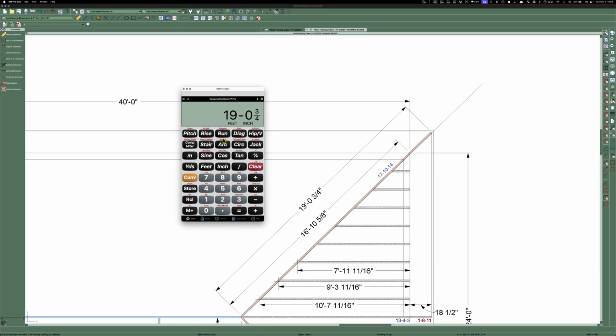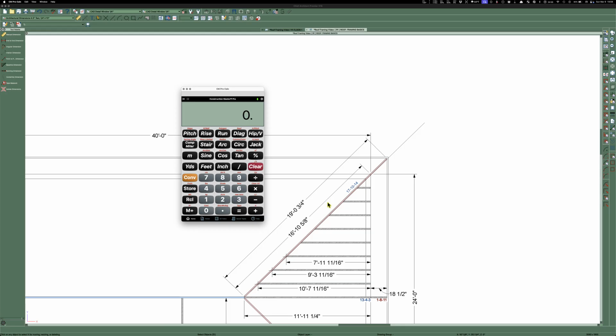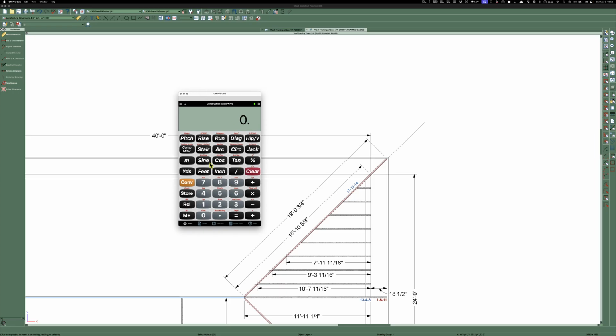I wonder if it'll let me do this. Yeah, hold on. Because really, people will say it's 17. It's 6 and 12 for your commons and 6 over 17 for your hips. But it's not really. It's the square root of 288, which is 16.9 something. And I'm used to my actual HP calculator. I wonder if I have that on here. What is it? EMU? Yeah.